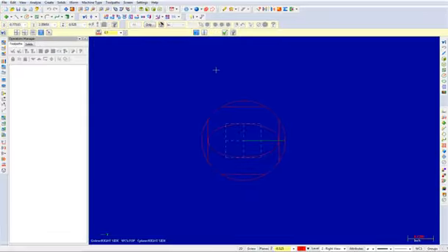Now select the OK button to exit the command. Your part should appear as shown. Now we will break the lines using the command Break Many Pieces. This command allows us to break the geometry into a desired number of pieces that we wish, and automatically calculates the length based on equal lengths or rounded distances.